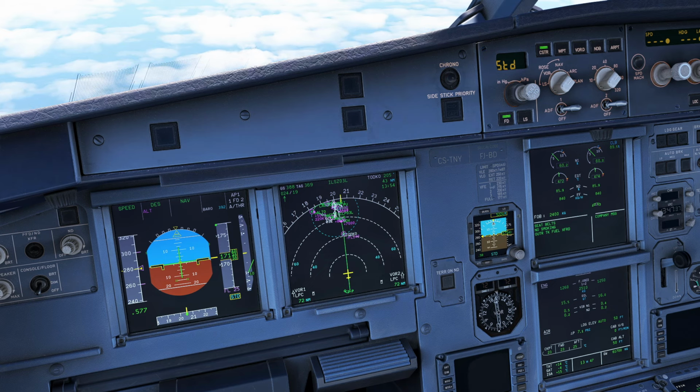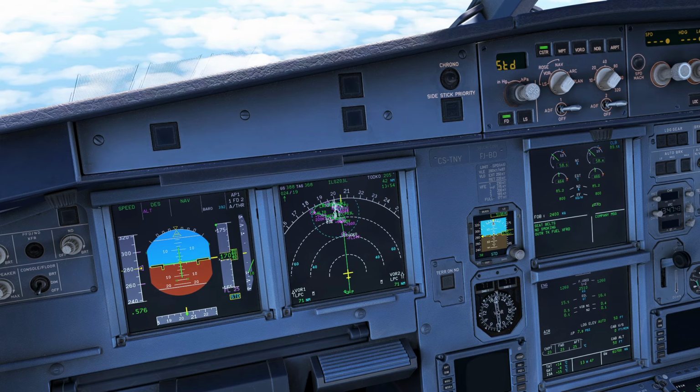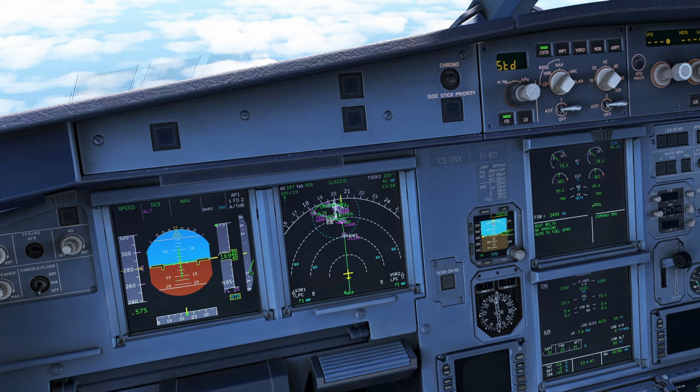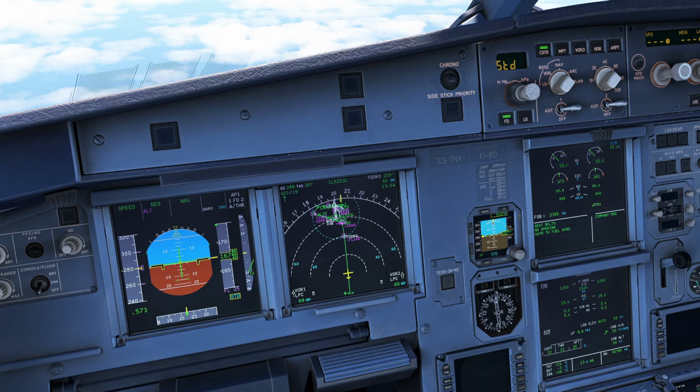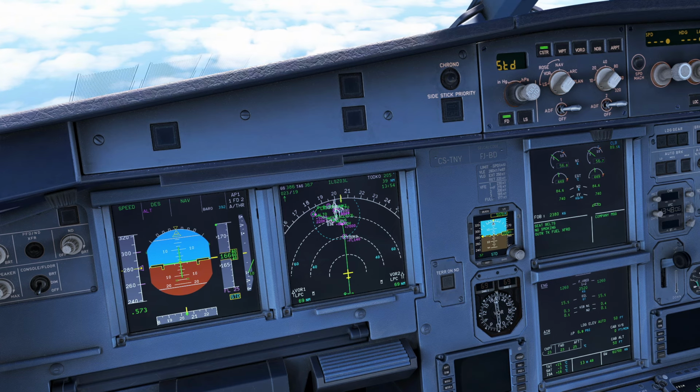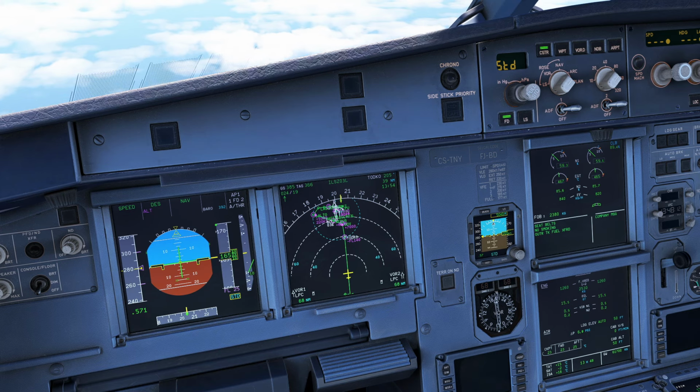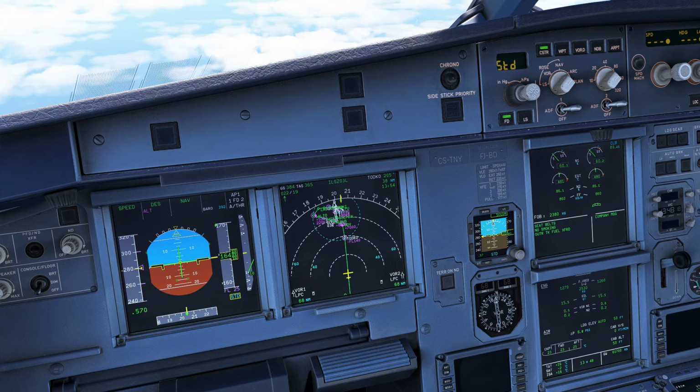For fuel efficiency, the decelerated approach is much better because you fly toward the last stages of approach in clean configuration or a lower selection of flap or slat, but early stabilized approach has slightly more fuel consumption due to the drag of configuring the aircraft earlier and also lowering the gear, and you are flying at a lower speed during the approach.